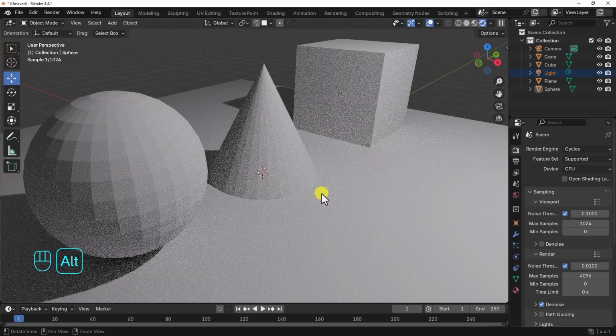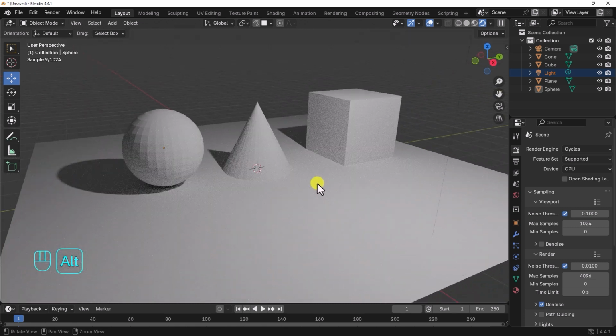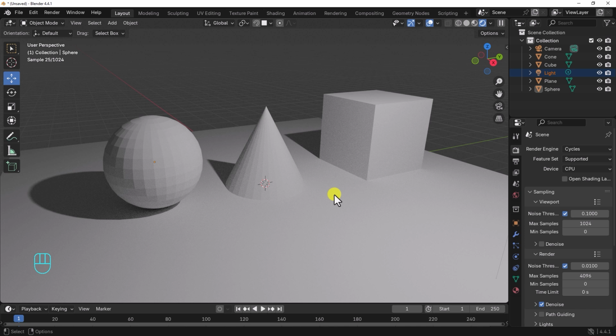When I work with materials or textures and lighting in a scene, I almost always use Cycles as I work, so I can see a very accurate representation of what I will see when I render out a higher quality image or animation. Think of this mode in the viewport as an IPR render in Maya, updating in near real time as you edit materials, or lighting, or move around the scene like this. The quality settings, which affect the redraw time, are below in the sampling drop-down.